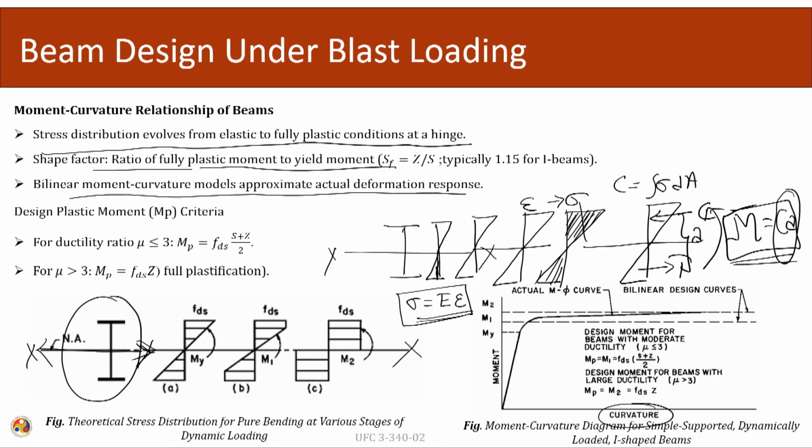If you look into the stress strain curve, let us say this is for a steel type of material. The material used is steel. So, first of all, the material will remain in the elastic region. After the elastic region, it will go into the plastic regime. So, we approximate this by an elastoplastic curve.